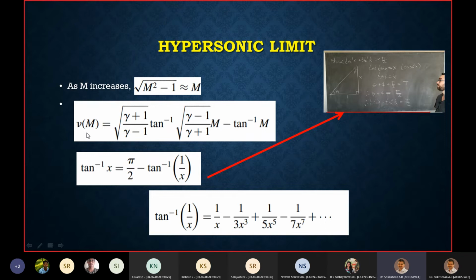Anyway, that's okay. Then this tan inverse x again can be expressed as a series: 1 by x minus 1 by 3x cubed, etc. And as usual, we'll neglect all the higher order terms because x here is Mach number, right? Pi by 2 minus tan inverse. So we have tan inverse m here, so both the terms have m, and this x here will have a term containing m.